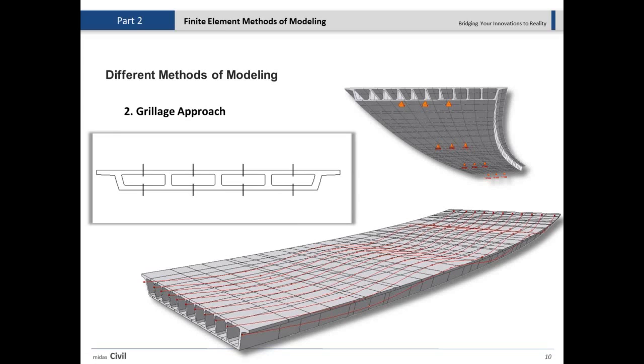So we have to consider each of these parts as a single beam element with the shapes that you see right here, and then we see the effect of them. We ensure that they are transversely connected and working as a unit system. They are not working separately. And as you can see, we definitely have to apply the post-tensioning or pre-stressing tendons along the webs as well.